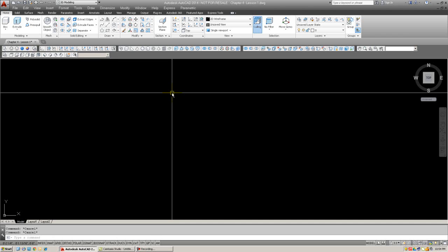The basic idea is as following. We would like to draw a 2D outline of an object and revolve this outline or profile around an axis. If the profile is closed, the result is a solid of revolution. If the profile is open, has gaps, or lines are used instead of polylines, the result is a surface of revolution. This process can create some unique shapes that are impossible to make any other way, but the entire concept rests on the designer's ability to visualize the profile on which the model is built.